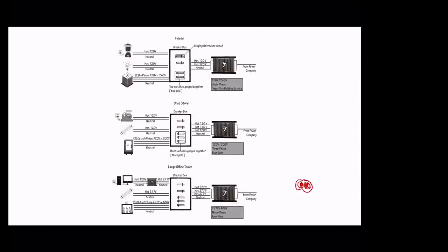So the electrons are moving out this way, and then they're going into the electrical receptacle, through the wire, through the motor, back through the neutral, through the breaker box to the neutral, and then into the ground, which is kind of a weird thought. This is different than the ground. There's also a ground wire, but that's actually different. This is the neutral, which is grounded, not to be confused with the ground. I talk about this quite a bit in the Amber book.